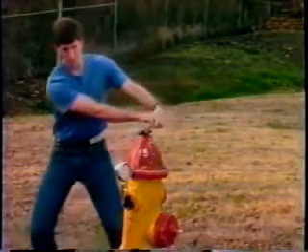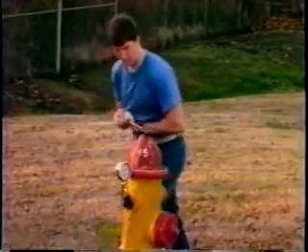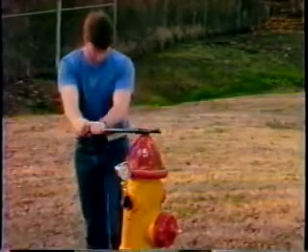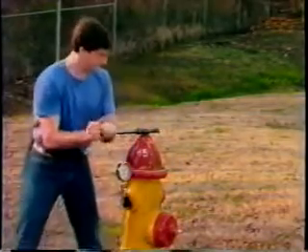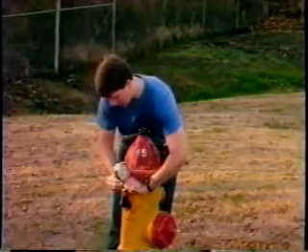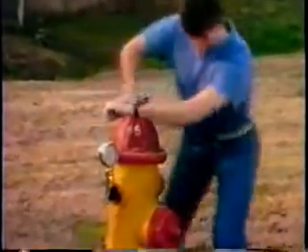The person at the float hydrant must open the hydrant very slowly. It's very important not to cause abrupt changes in velocity in the water distribution mains. Therefore, don't open the hydrant quickly. Open it very slowly.